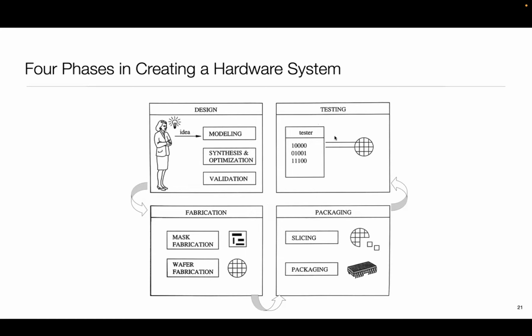Some other chip instance, maybe a day later or on a different wafer, came out to be better performing, and that gets slapped with a higher performance number. So testing is also doing what is called binning. It's grading the chips based on their performance and putting them into different bins so that we can make more money, right? I mean, the other alternative would be to sell only chips where all the chips are guaranteed to work, but then I leave money on the table.